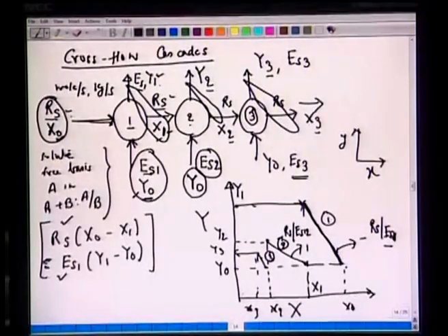And more important, say there is an equilibrium curve like this. Also important to note here is that this is very similar to what we had in case of continuous contact process. So in continuous contact process also, if we have two streams flowing concurrently, and we give them enough residence time, then the leaving streams will also be in equilibriums. But it's a continuous contact process, so there the operating lines, we can assume that it's continuous. Here, since we have stages, in one stage, two streams come in contact, they spend time, and the leaving streams are in equilibriums.